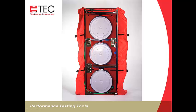So we'll connect them, and with a 3-fan system, you get a tubing kit that includes all of these proper lengths of tubing for this connection. And so we're going to tee together some connections here to connect the 4 fan references to the blue tube, and we'll run that off to the side. It's got about 12 feet of tubing that allows you to get that out of the turbulent area.